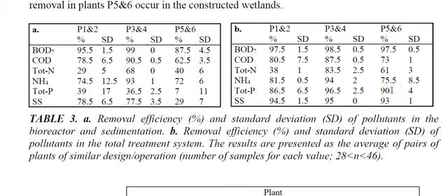And we know that phosphorus removal is a fairly complicated process, whether it's done biologically or with chemical means. So at small scale, you don't have the equipment or the people to run it, but by adding the passive wetland, we still can achieve very high phosphorus removal. So these techniques are especially suitable for small scale treatment.